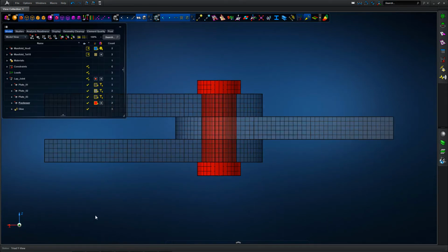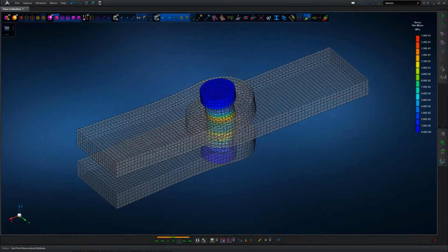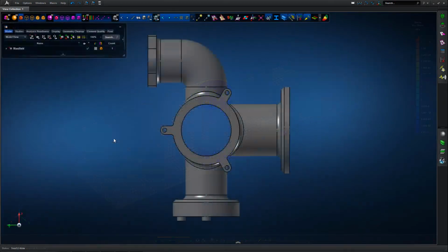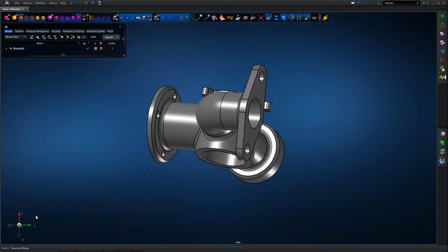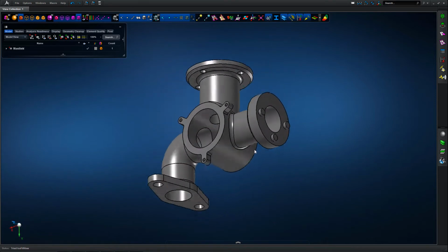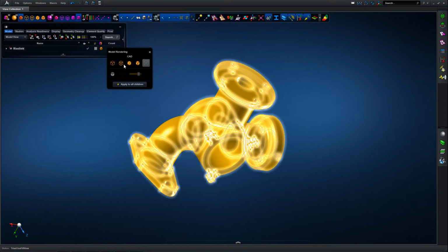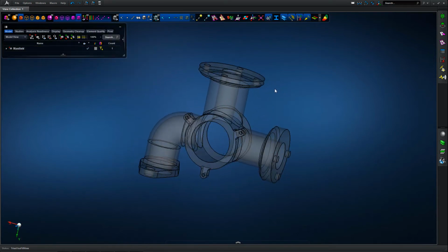Shown in wireframe we can see the fastener and how it protrudes through the assembly, and we can run an analysis. In this instance we've used a linear static analysis, but we could use non-linear tools if necessary, depending on what we're trying to achieve. Looking at some perhaps more complex real-world geometry, and again this is going to take the form of a target for hex mesh definition.